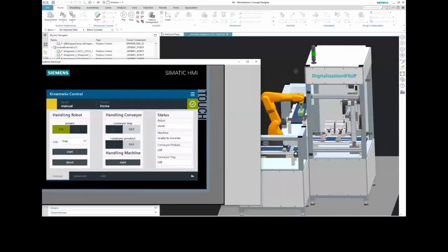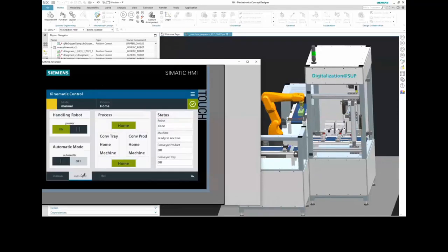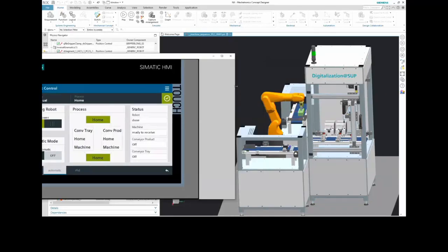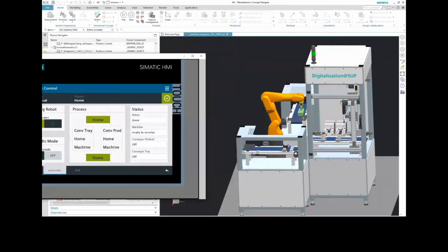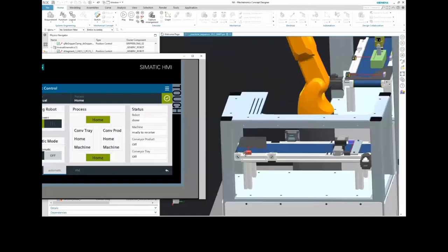So, well, we see it can move manually now, so I can try to move it in the automatic mode, and I can see, for instance, it performs some sort of sequence in automatic mode. It goes and picks up the tray from one of the conveyors, and all the parts that are coming down this conveyor go through some sensors, so they can possibly be some RFID sensors, which we can then simulate in Simmet as we saw earlier, and we can give that feedback to the PLC.